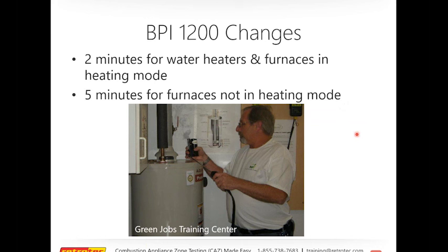So the question is, no more drilling into the flue and checking if the flue is more negative than the CAZ, correct? That is correct, Andre. I know earlier I said that I can't give you too many specifics or detailed answers, but what I can tell you is that that is a pretty general question. Yes, there is no more draft testing. There are no more draft limitations. We're not concerned with that. You're welcome. What we're really looking at more than anything is setting up the house into a worst case depressurization scenario for the combustion zone, and then testing for spillage.